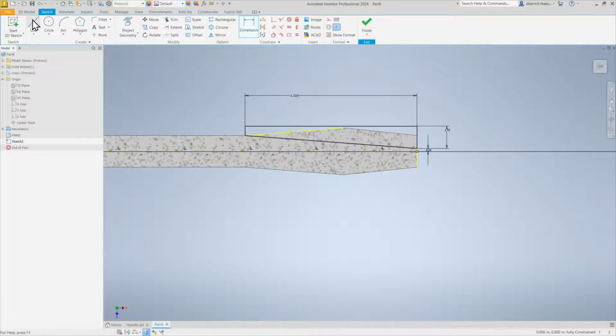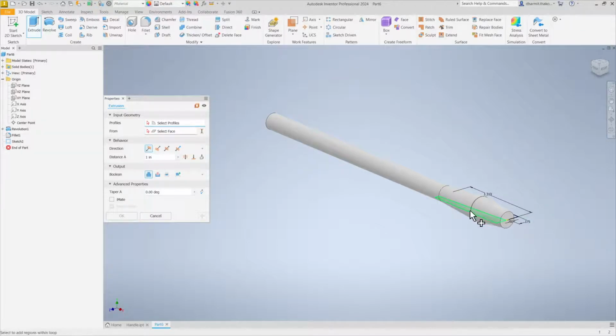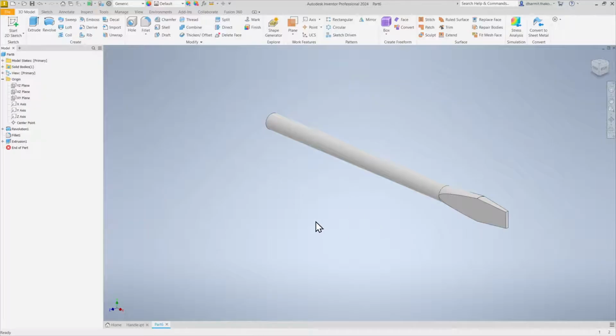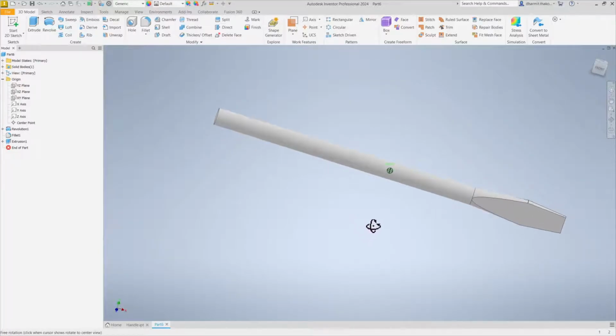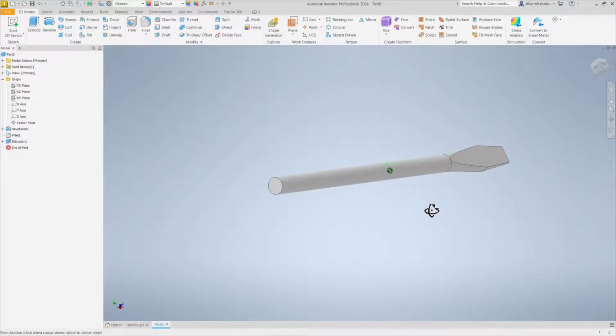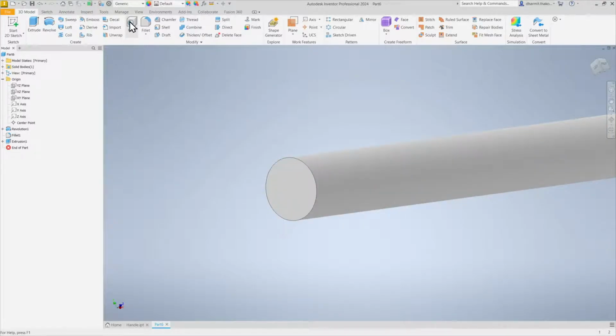What we'll do next is create a center line here, and then we will mirror this entity that we just created, and the mirror line would be here. Click on apply and you get the mirror out. So finish, and then you can extrude these two profiles, and you need to cut them both sides, full cut. When you do that, you can see your driver bit taking shape.